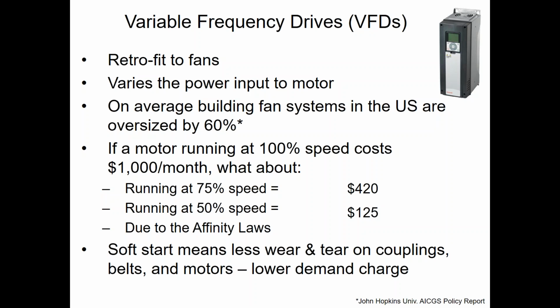Normally, when I turn an AC inductive motor on, it goes from 0 to 60 miles an hour in 1 second. Boom, bam, it's all on. And I get all this extra torque applied, which does a little bit more damage to my belts and to my couplings. And then I also get that loud expansion noise in the ductwork, and all of that kind of stuff. With the VFD, that's not the case.